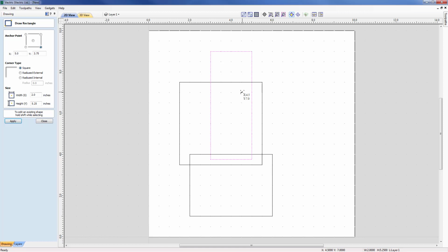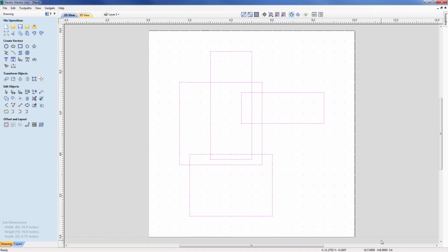And similarly, if I want to change that and maybe specify the correct distance in Y, but I want to be 4 in X, then I could just type 4x, and that will give me that parameter typed through the keyboard. Okay, so we've explored the rectangle options here, so let's close the form down now and delete out the vectors, and now we're going to take a look at Polygon.